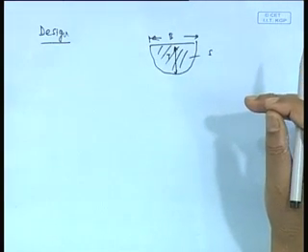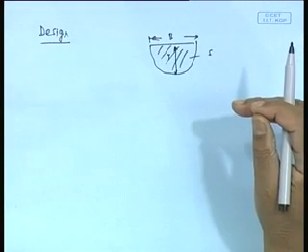What I am saying here is that in order to do an elementary or initial Seakeeping calculation, you do not have to have a very exact hull shape. Even if you have that, you are anyhow going to make an added mass and damping calculation, which is approximate. Therefore, there is a general consensus that it should be made a routine part of design.